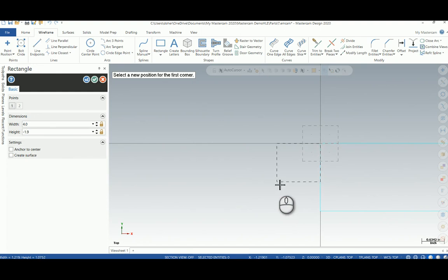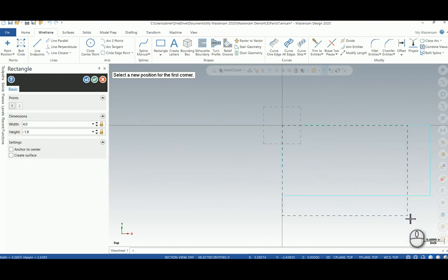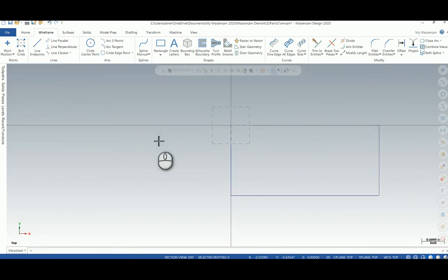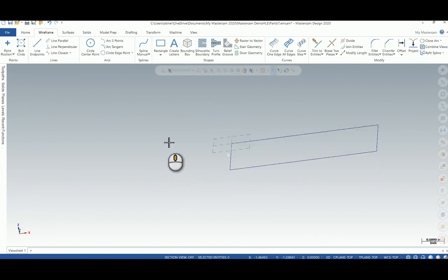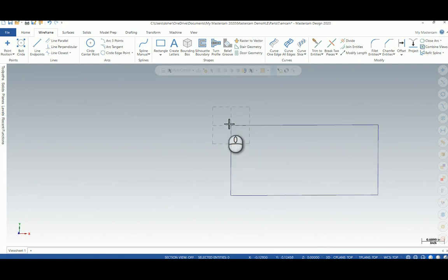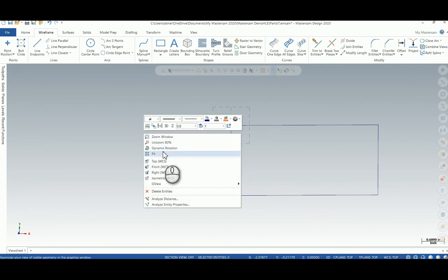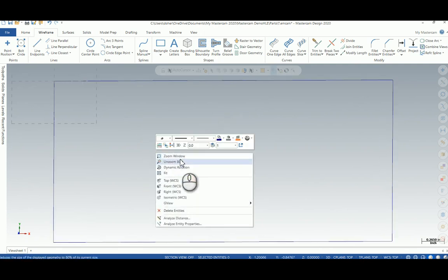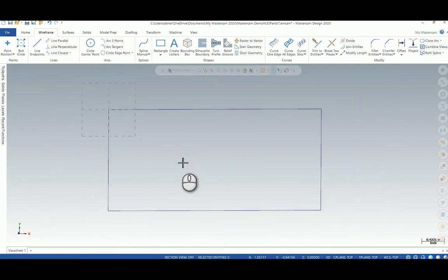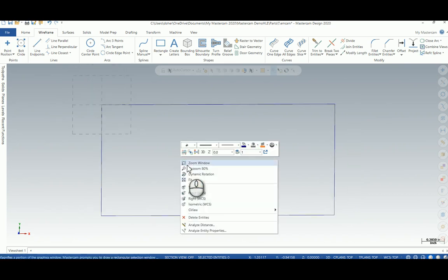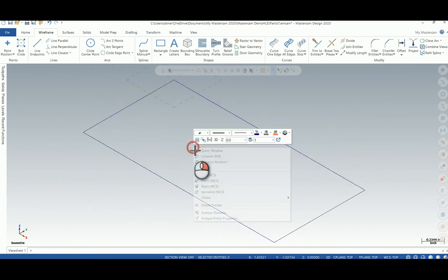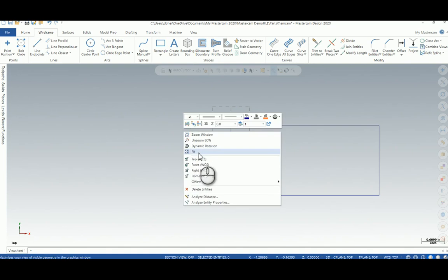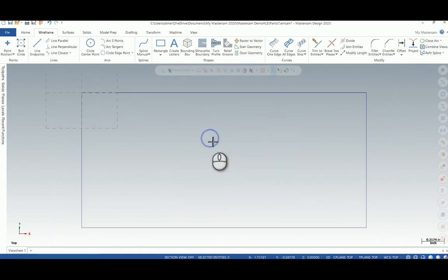All right, so now it's made a blue box over here. Right now it's trying to draw another rectangle, so I'm just going to hit the green plus. I'm done with rectangles. And I can even turn off my F9. So this is my XY plane coordinate. I'm going to hit the fit button, and now this resumes. And I like this unzoom 80% button, or just roll your mouse in and out. So I'll go between that and isometric view. Top, fit, unzoom. Okay.